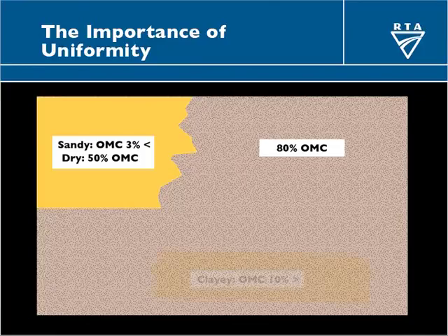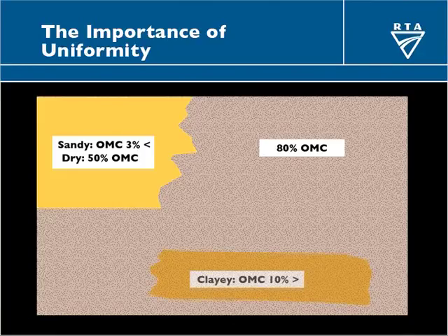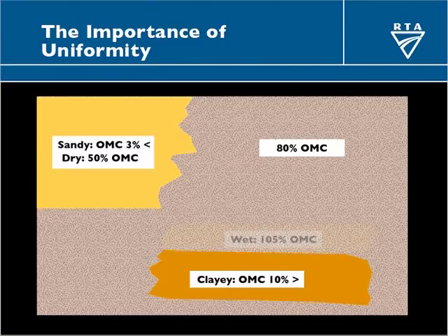Now, suppose there's another variation, the other end of the fill. You've come up with something clayey. It's also a bit drier, but you can see that as it comes out. It needs water added to it. Suppose you've done that. Okay, fine. You've got it to a similar condition to the bulk of the lot, and you're hoping your compaction routine will still work on it. But your water carts have sprayed over the edge of the clayey material, and you've now got a wet strip in there. What's going to happen now? Your compaction routine will give you an unstable area there along that strip, and it will start heaving.